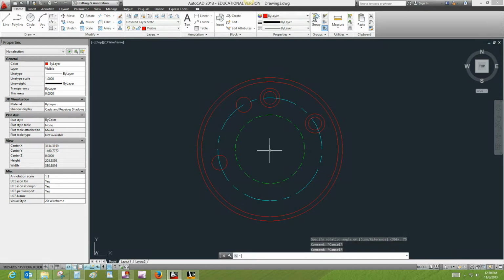Now the hole over here, it appears to actually be mirrored across. Okay, and if we do a little bit of math there, 45 plus 60 plus 30 is 135. The hole over here is located at 105. Oh, well, actually, the 60 plus 45 and then 30 plus 75 are both 105. So yes, this other hole is mirrored across.